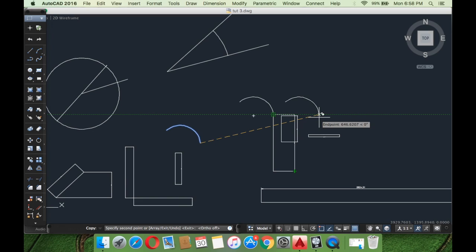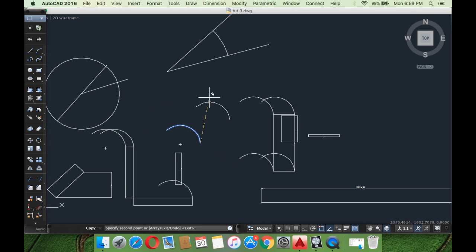You must remember that as long as you don't press enter or right click and enter, the copy cursor will hold the object that you had selected with respect to the reference point. Now see, I can draw as many arcs as I want to. Suppose I draw an arc over here, over here, and whatnot. Each time this particular arc gets copied, so I press escape and undo the complete thing because it looks clumsy. You can do the same for move even.